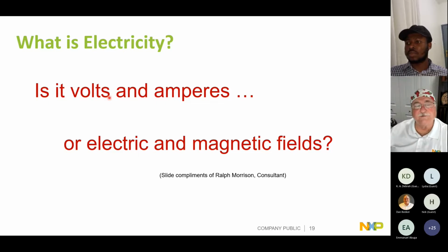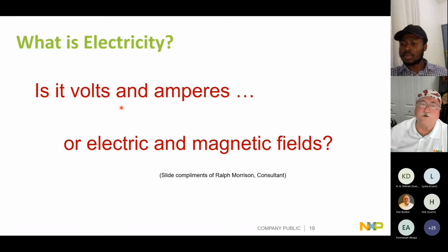So, to take it a little farther, one of the great tools that we have is an oscilloscope. An oscilloscope lets you look at changes in voltage over time. So you take your oscilloscope probe and your ground lead and you hook it to your circuit board, and you can see changes in the voltage over time. And it looks pretty interesting. But again, it takes a finite amount of time to fill the space between the ground lead and the probe, faster than your two big long leads on your voltmeter, but it still takes time.